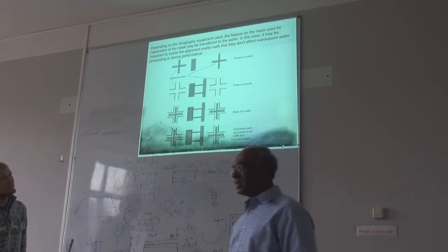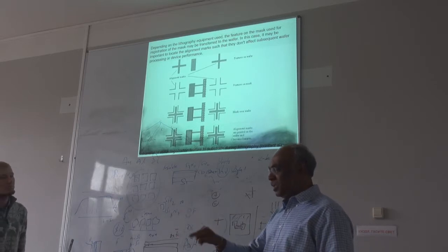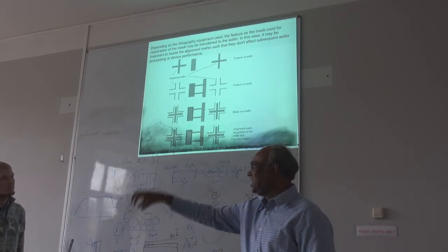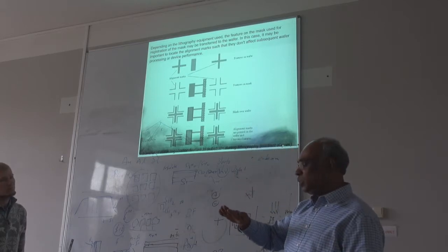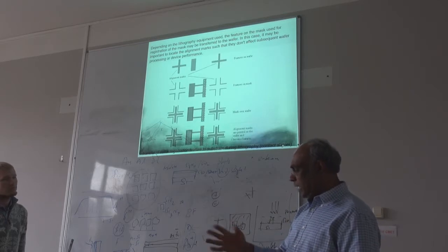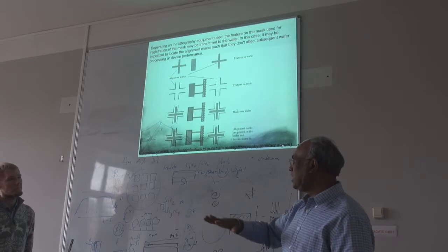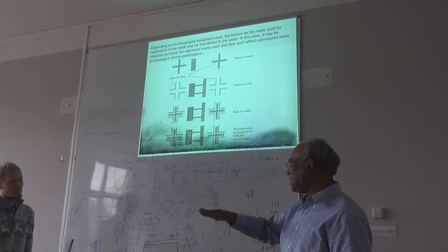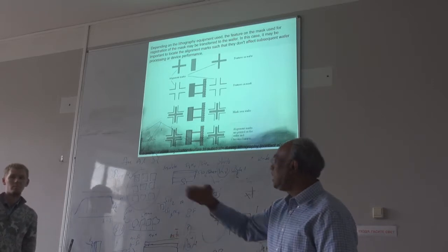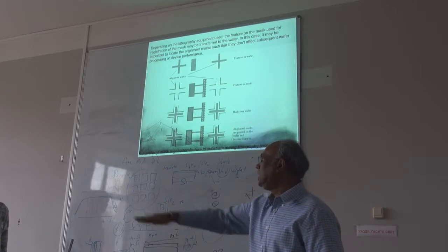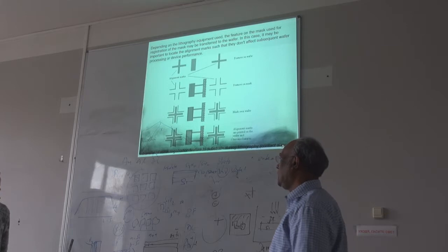But the important thing is, you don't make this feature on only one device. You have to do this several times. That's why with the resist, once you develop and etch, only those parts get stripped. But the rest of the resist is still good, right? So then you can move your wafer to a different position and repeat that. So that means in one shot you can make maybe 50 devices.